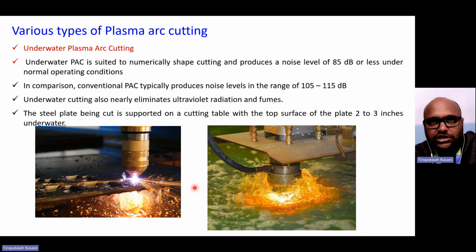The material removal mechanism is erosion. The second one is ultrasonic machining, where the abrasive particles are hit by the tool, and those particles in turn hit the top surface of the workpiece, removing the material. The material removal mechanism is brittle fracture.